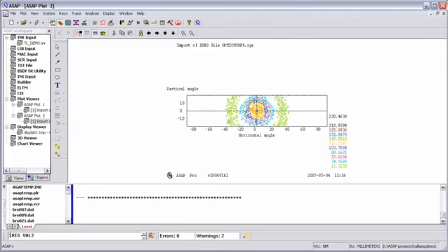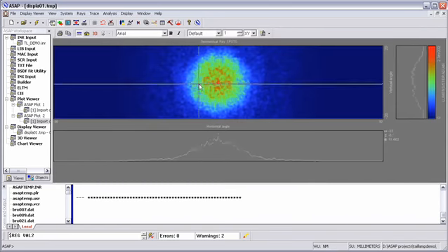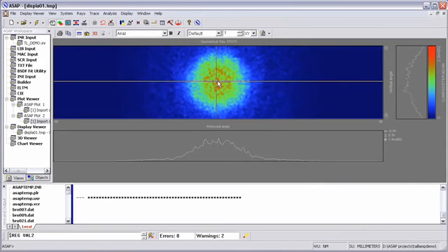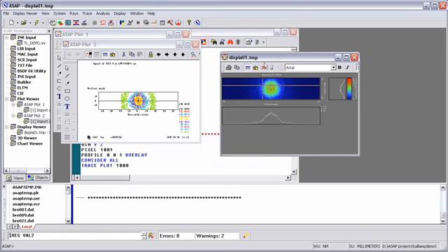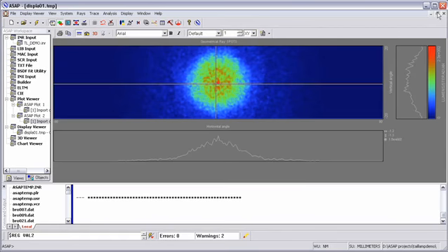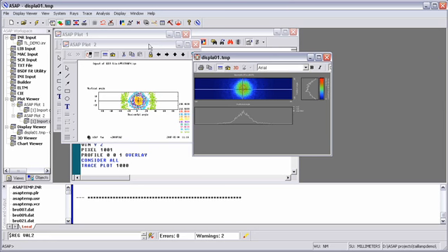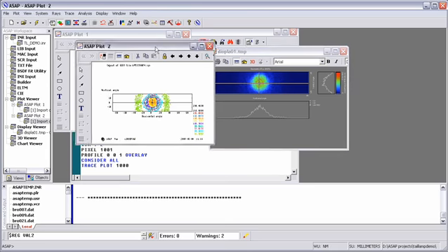What we've also put out, which may be a little more familiar, is an isocontour plot in the angle space of the turn signal, so we can look at the angular contours, as well as a picture plot where we can interrogate individual pixels if we want to look at specific values. You'll notice that the resolution for this particular demo is a little bit low. We've traced a smaller number of rays than we would normally trace for an entire simulation. If we wanted to do the final output on this, we would run upwards of 3 million rays. In this case, we've run only a couple hundred thousand. The 3 million ray trace might take 45 minutes to an hour to complete.